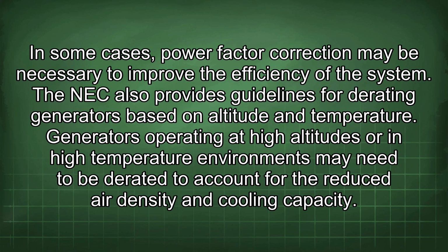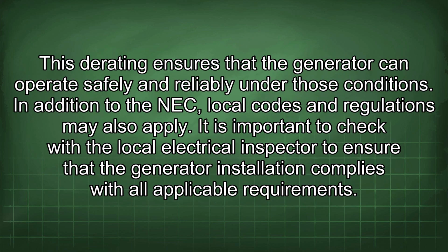Generators operating at high altitudes or in high temperature environments may need to be derated to account for the reduced air density and cooling capacity. This derating ensures that the generator can operate safely and reliably under those conditions.